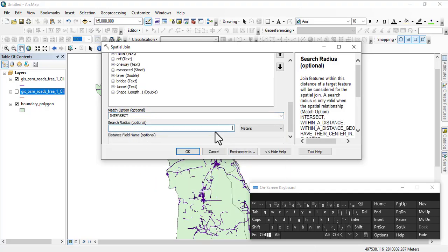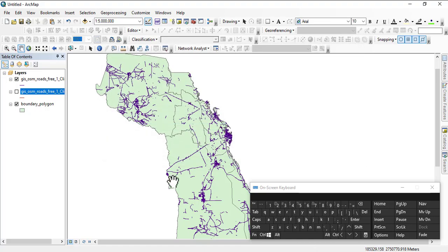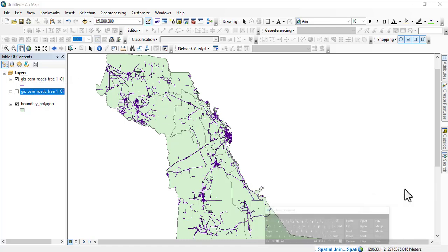You also add a search radius, let's say 5 meters, and if we are done with that, we just click on OK. So this should be able to import the attributes we've lost from here into this one that has no attribute, giving us both the repair and the attributes we had lost. Now we have retrieved them.